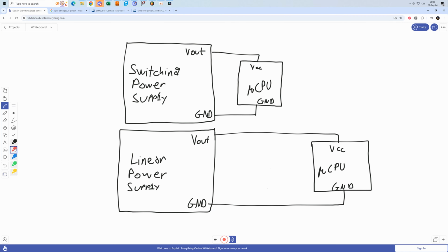So as we have seen, it is absolutely crucial that we power our microprocessor from some very stable voltage, meaning that it cannot ever be powered from a switch mode power supply, because switching power supplies create a lot of EMI, or electromagnetic interference, and that is going to cause all sorts of trouble, especially if we are using the analog features of the microprocessor. So we usually want to power microprocessors with linear power supplies or batteries, and this usually renders much better performance.